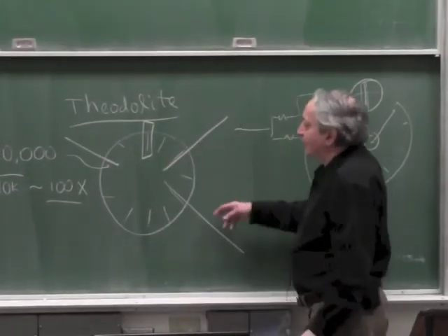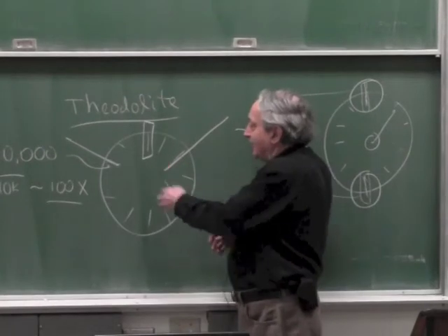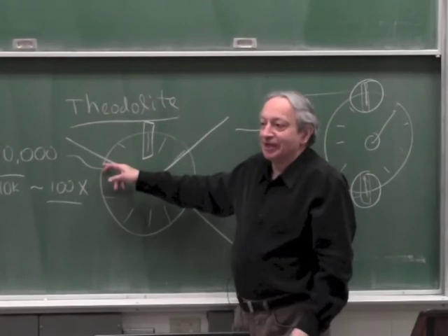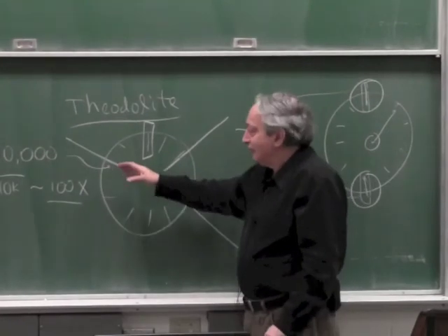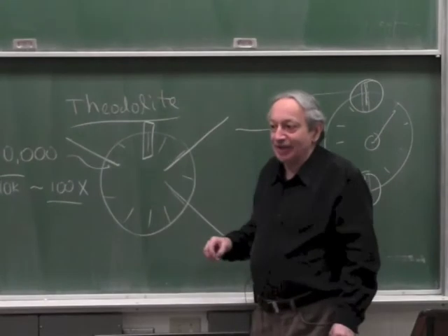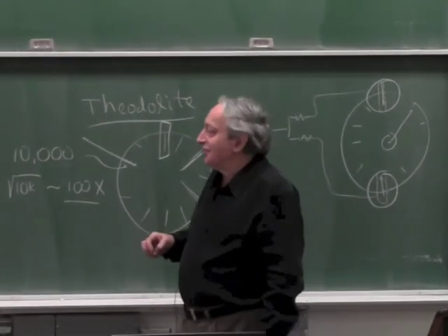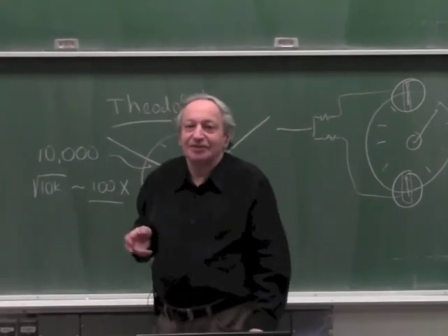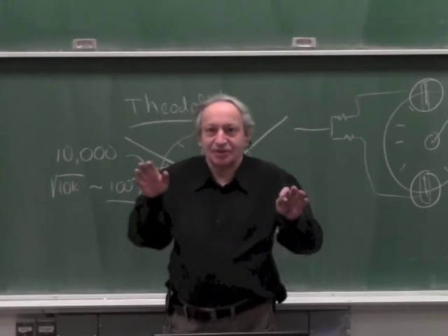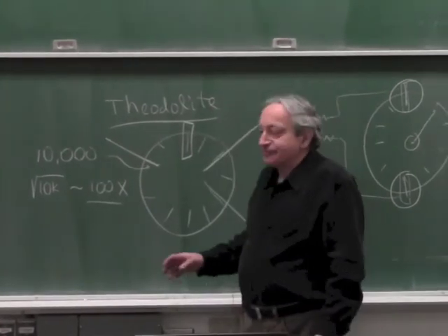So you have 3 microscopes at random positions. And now, if you rotate the wheel, if it's perfect, if one microscope lines up, the other 2 will line up. If it's not, you have to file the gears until eventually, at any position, the microscope will line up. And using this and 6 months of patience, he achieved better than 1 arc second 200 years ago. Okay? So that's all of this we went through, it's just a refresher. So now let's move on.